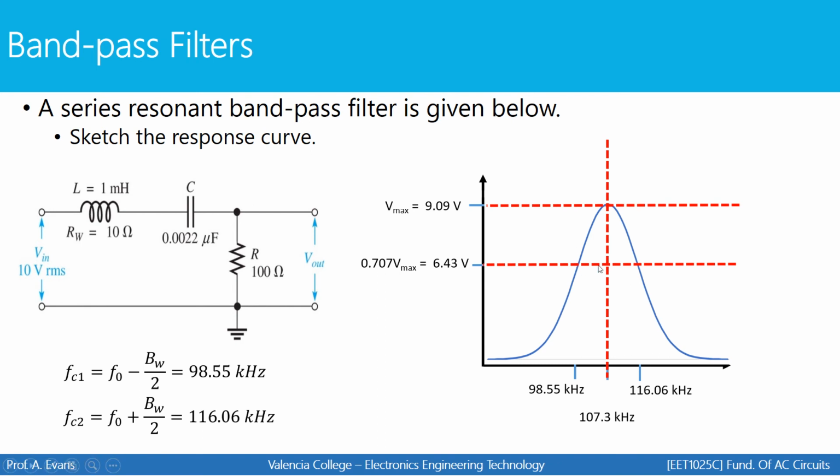So from this point to this point, these are all the frequencies that are considered to be passing, and the voltage that you will measure at the output we can read from this graph. So if I were to input a frequency that's maybe right about here, I can use this graph to determine what output voltage I expect to measure from that particular filter. Frequencies that are outside of the pass band are considered frequencies that will be rejected. They do not pass through the filter.